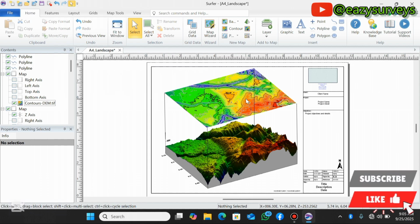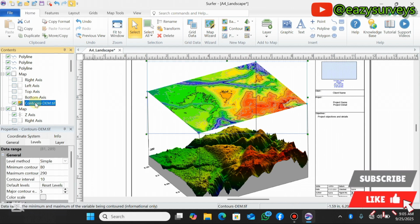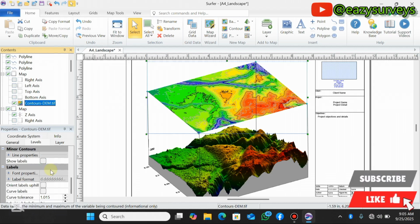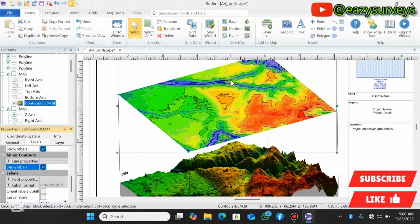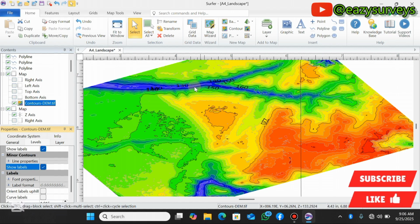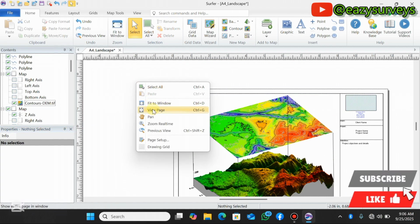So that is it, guys. You can definitely make changes to the contour. If you want to make changes to the contour, you select the contour, you can change the contour interval, you can increase the major contour, and you can actually let it show labels. So you can click on show labels, and it's going to show the labels of the contour. If I zoom in, you can have a view. You can see the labels of the contours. So that is just the idea of creating a stack map.